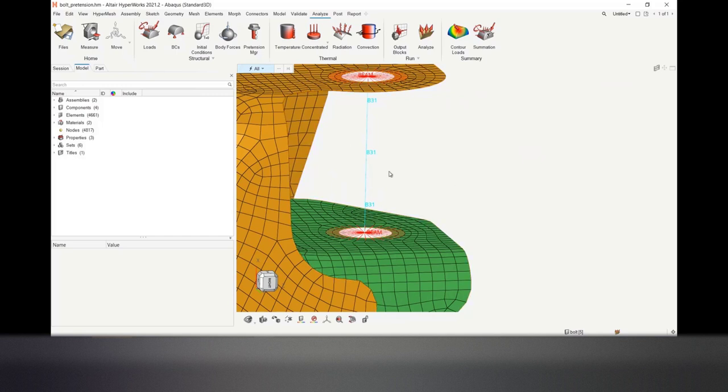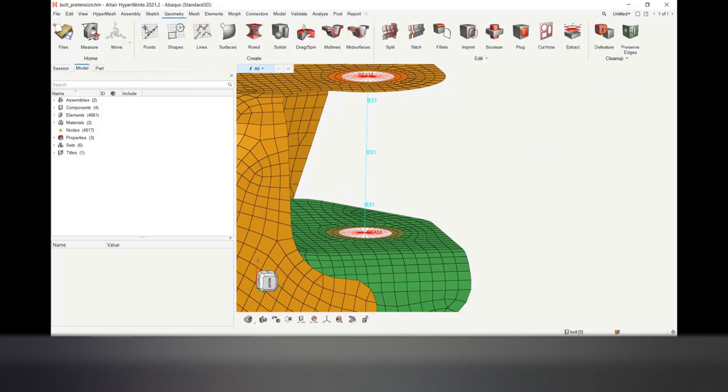We have to have some node that helps do the pretensioning here behind the scenes. So it can actually be, I think, anywhere, but just for ease and kind of model management, I'm going to put it in between these two nodes so I have some idea of what this random node in a larger assembly might be doing.